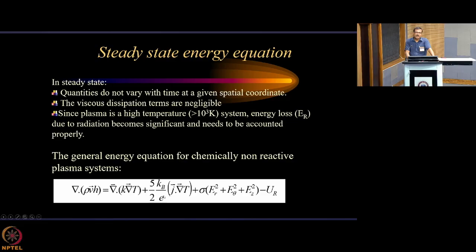Now, in case of fluid flow, you know that it is probably a bit more convenient to handle those systems using the finite volume approach. So what you do, you take those differential equations and integrate them over your control volume, and then you solve those equations. So that is basically the finite volume approach.